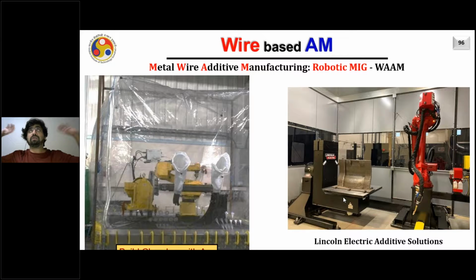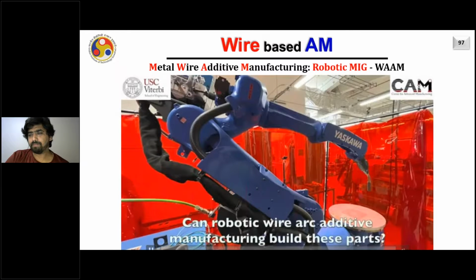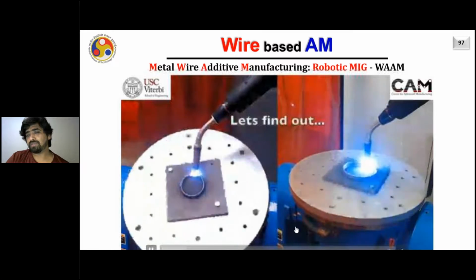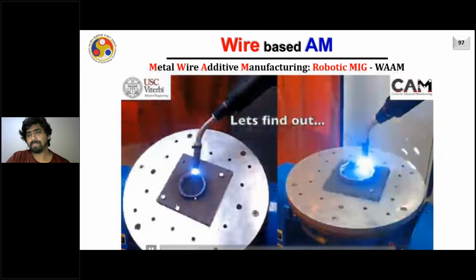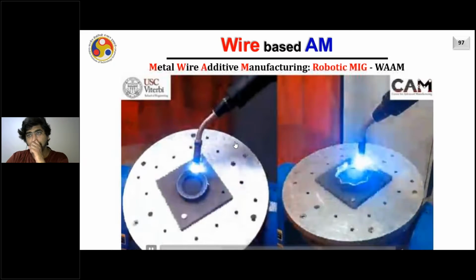But what if I just turn the roof upside down and then do the welding in a conventional horizontal manner? That makes the process easier on the welding side, right? So in a very similar fashion here also, if you use a tilting table, then you can tilt the part and do the welding easily. This is a MIG welding based 8-axis robotic system. As you can see here, there's a tilting table and rotary table, 2 axes, and a 6-axis robotic arm.